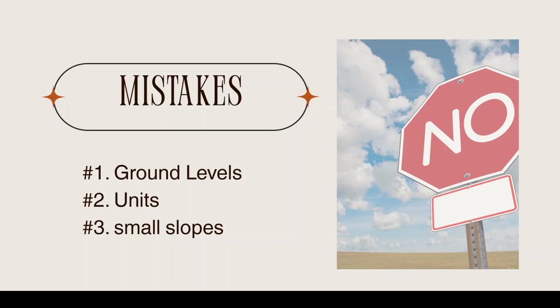That is why in practical application, we solve all these problems by first doing a topographic survey, whereby we survey the land to come out with the right profile. Then from there, we can do some analysis on the profile or on the surface, and then decide on the best slope that we can adopt to minimize over-excavation and also to ensure efficiency of the system.